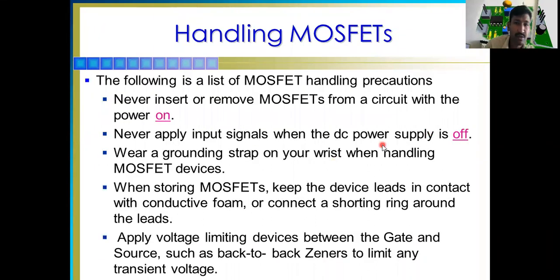Okay. Now, how to handle the MOSFET? I have written some points here. The following is a list of MOSFET handling precautions. Whenever you use the MOSFET, you cannot directly touch it with your body. Never insert or remove a MOSFET from the circuit when the power is turned on. You cannot remove, touch or insert the MOSFET while it is powered on.